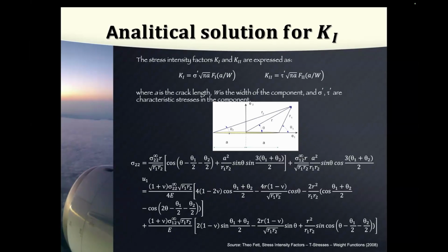But with the numerical approach, we can easily handle these formulae. You program them once, you write your own code, and then you can run as many simulations as you want. And the best thing is, look at all these equations here. This is a CCT specimen, with a crack in the middle of the specimen. These are the solutions for the displacement of the crack surface and the stress field, sigma 2, around the crack tip. And this is only for this kind of problem, when you have a CCT specimen.